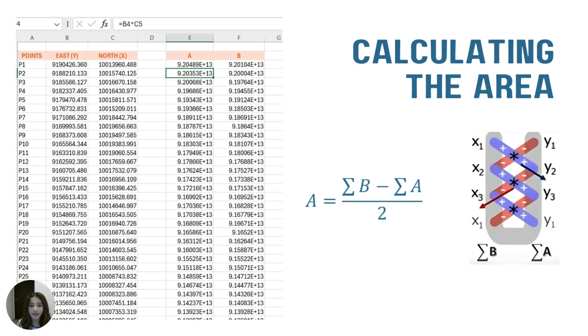So for calculating the area, what I did was import all my coordinates after converting them into a format which is easier to work with, with east in Y and north in X. So I did my whole table in Excel converting those coordinates. And after that, I used the following formula, which is for determining the area of a polygon on a specific plane.